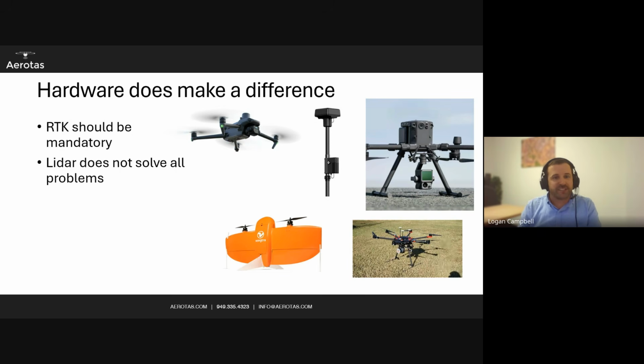You do not just fly a site with LiDAR and everything works. It's very expensive to process. It's often less accurate than photogrammetry, depending on a handful of factors in your own mission planning. A lot of people think they buy a LiDAR drone, ergo they fly every site with LiDAR. Not the case. Wonderful tool, but it is not the solution to all surveying problems.